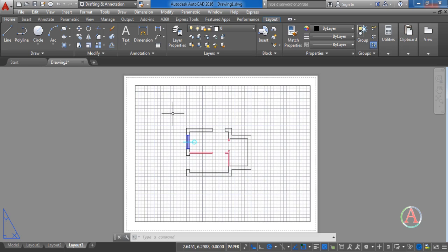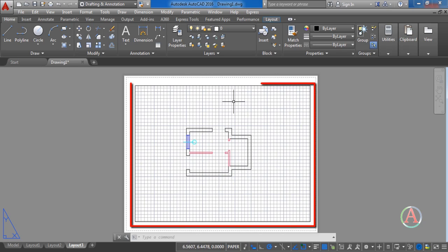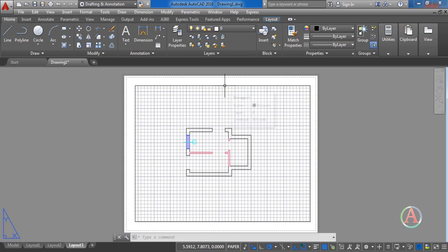Everything that you draw in model space is automatically represented in the layout, or the paper space. Working in the layout tab, you can create viewports. Here you can add the dimensions, notes, and a title block to represent the drawing sheet. This is the space in which your paper drawing comes to play. Every layout viewport is like a frame that contains the picture that you have been working on in the model space. That is the box over here, the viewport. Every viewport contains the model in the scale and orientation you specify.